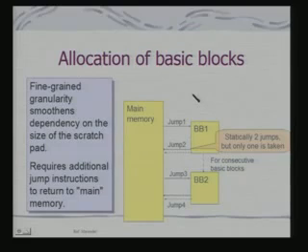It is found that by optimally mapping the blocks to scratch pad memory, you can have substantial energy saving. In many cell phone based appliances with GSM coder and decoder implementations, benchmarks have shown that migrating the code onto scratch pad substantially enhances battery life.